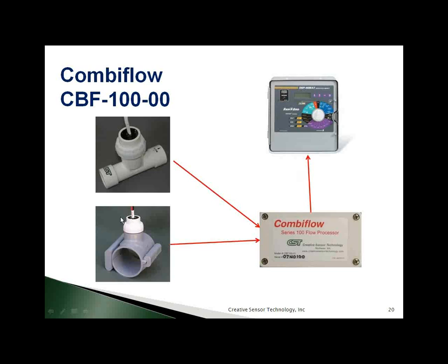These flow sensors don't need to be the same size. They can be different sizes. They can even be different types. And this is a programmable box that allows you to mix these signals and then put out a single flow sensor signal that appears to be one central signal.